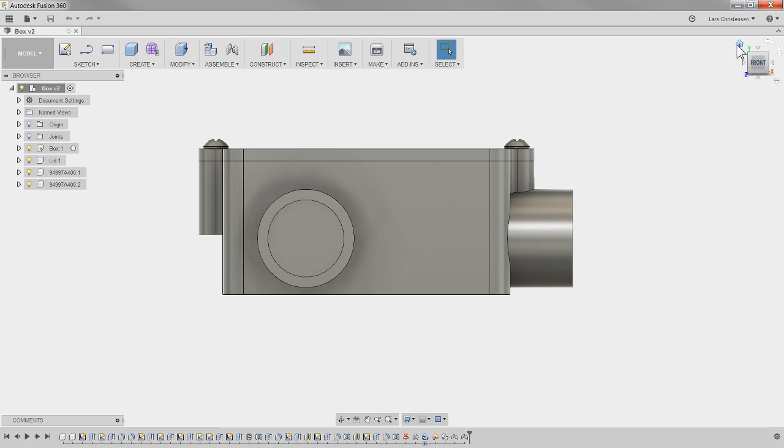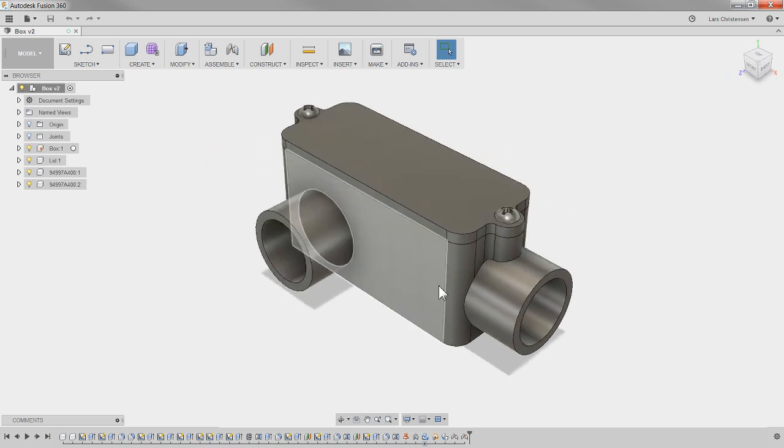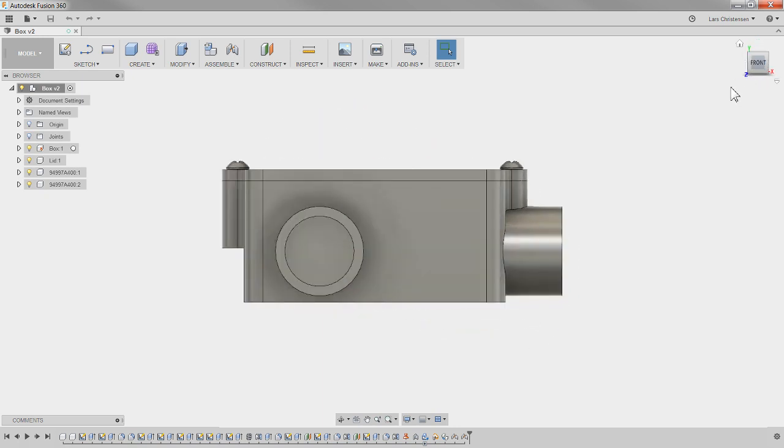And every time you go into an isometric view or something, it throws everything off. So how do you change this front to be top? And really all you're doing is you're changing the way you're looking at the part. Think about you are looking at the part almost like a camera right now. You're having a lens looking at the camera. We're just changing the lens. We're moving the lens. We're not moving the part around or the origin around.